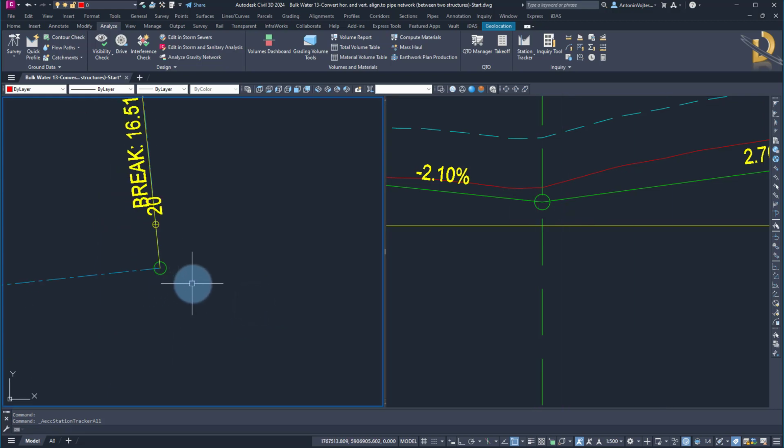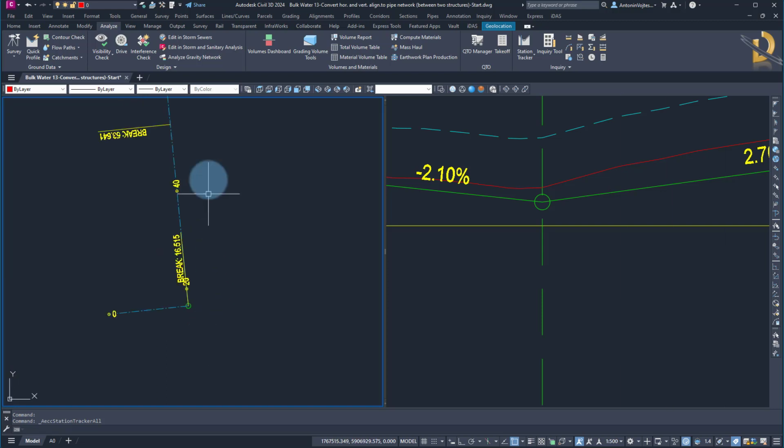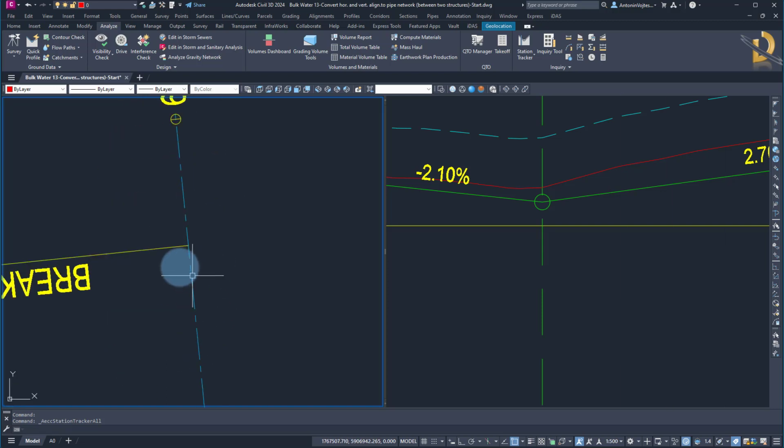So how to do that? I want them to be 1 meter from the air valve and scour valve. If I look in the plan, how can I measure? I can draw a line and then add 1 meter, but it sounds like a little bit too much work. There's a better workflow. I am using the scale 1 in 500.